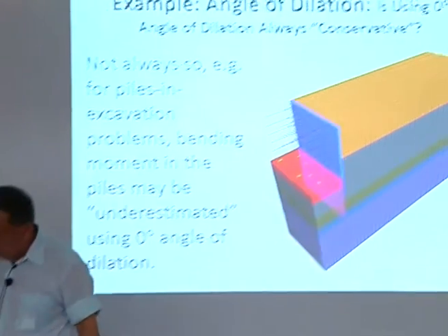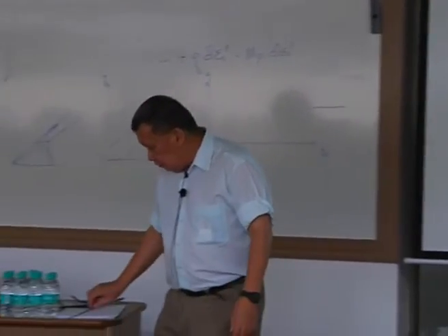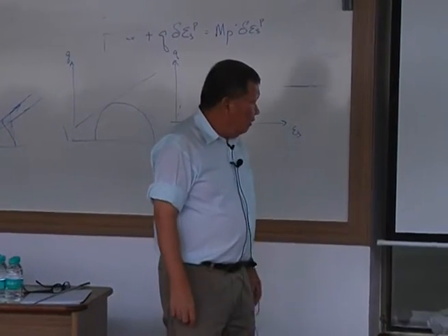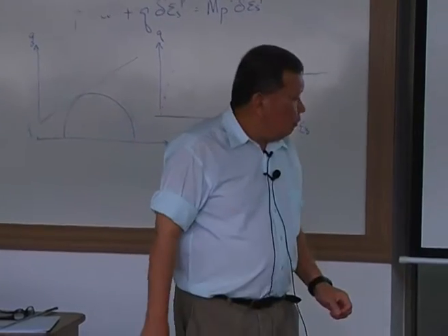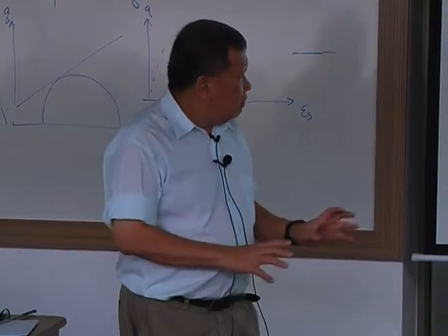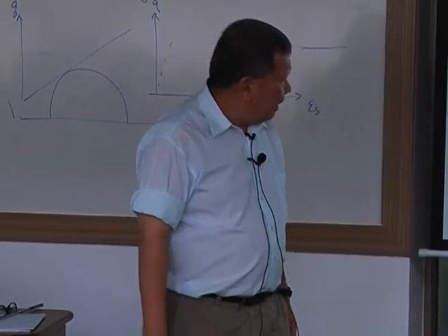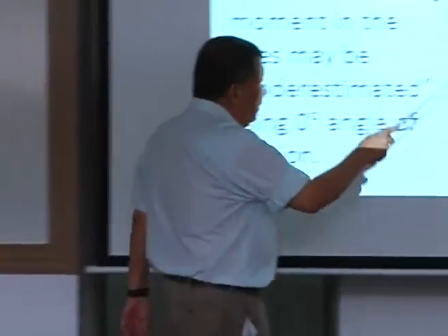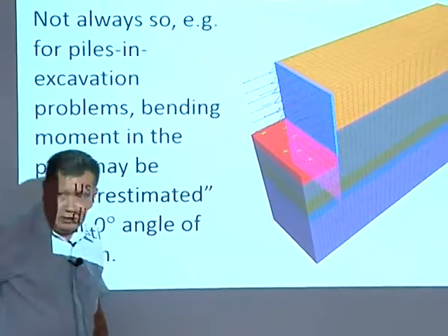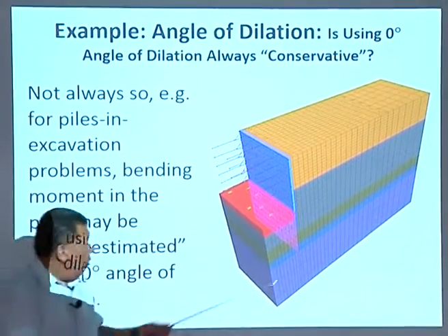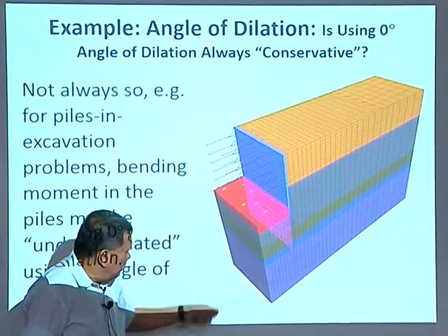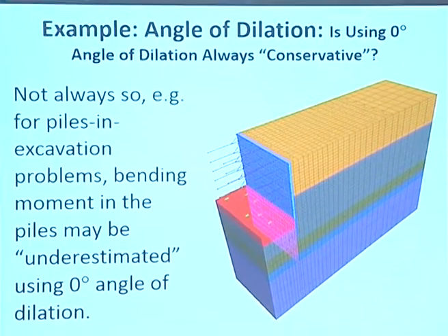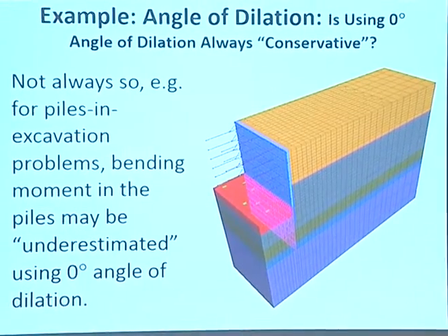So basically, you got a pile sitting through marine clay, and then with a reasonably thick layer of sand underneath. Okay? So I was using the Cam-Clay model for marine clay. I was using the Mohr-Coulomb for the sand layer underneath. And this is loose sand, because this is reclaimed land, and you can see a huge layer of loose sand over here. This is also sand. So I use Mohr-Coulomb here, Cam-Clay here, etc. So basically, it went through. And then I started to do my parametric analysis.